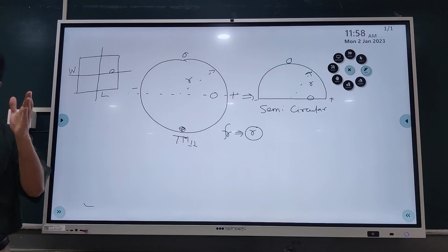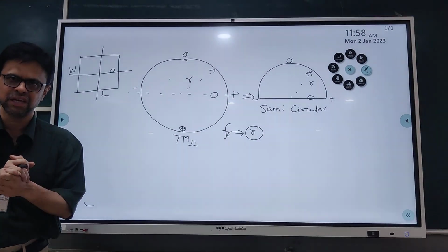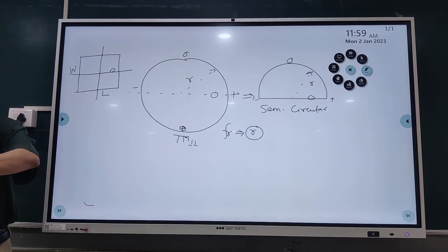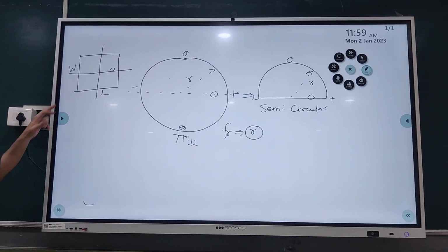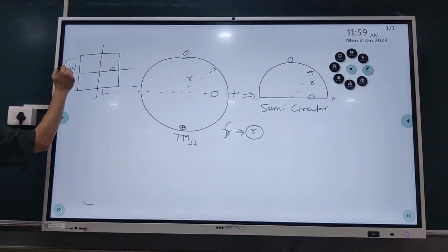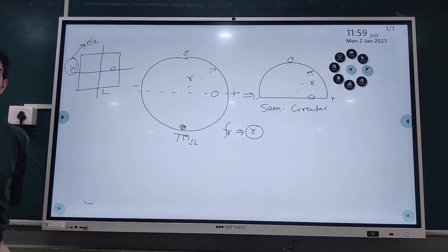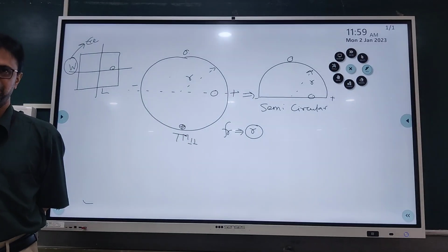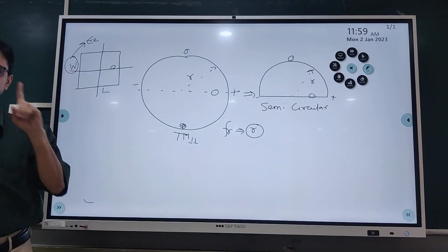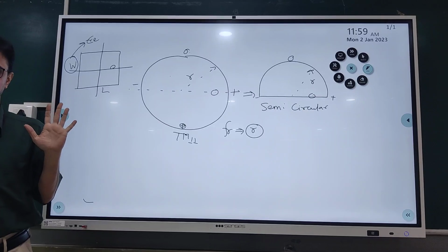Remember, with respect to the calculations of the patch dimensions in the rectangular microstrip antenna design, both the dimensions affect the calculation of the frequency. As we know, when we are calculating the length for the fundamental mode, this parameter has to be considered, as that directly governs the effective dielectric constant of the cavity. Whereas in this case, only the radius r, that is only one dimension of the patch, is governing the frequency.